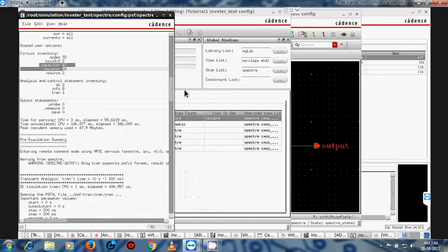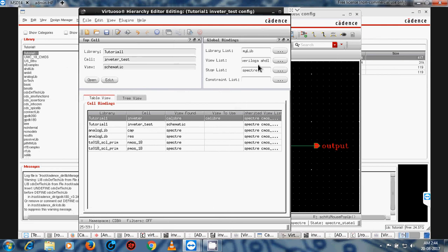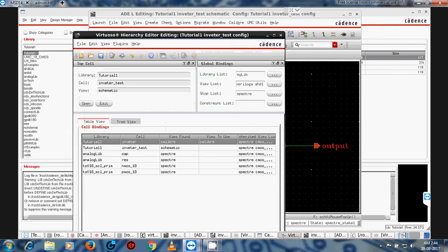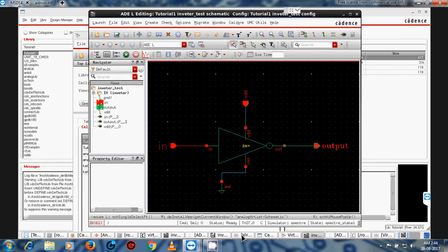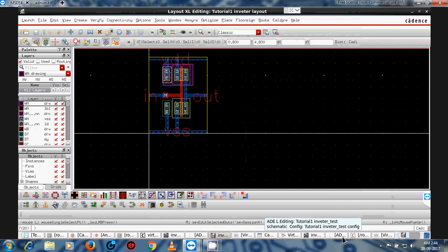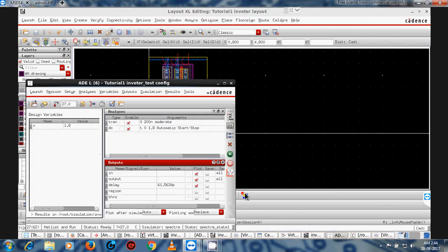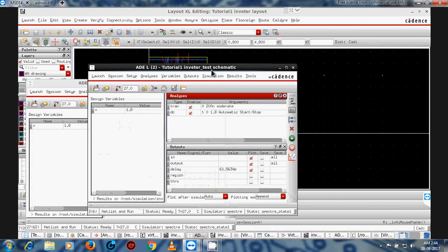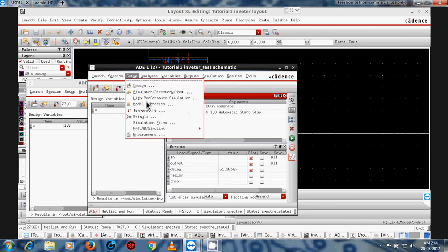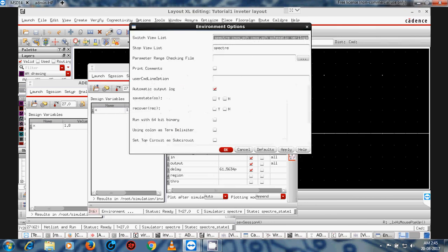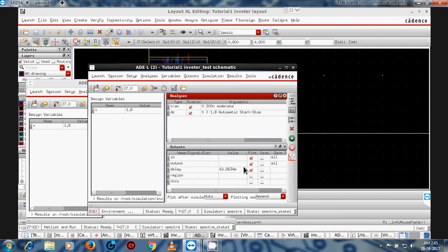Okay, so today in this video I will tell you four ways to do post layout simulation. The first one is by using the Calibre tool, and the second and third are using Virtuoso. So here in Virtuoso, in the second method of post layout simulation, just open this test schematic, change the environment, make the name, and run this. So it will show the post layout simulation.